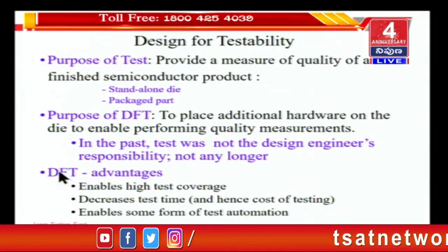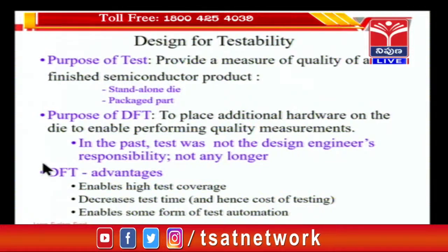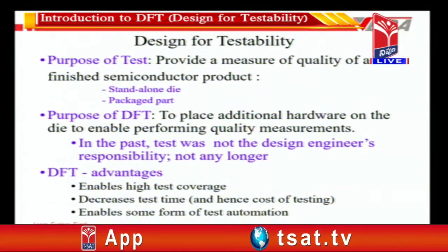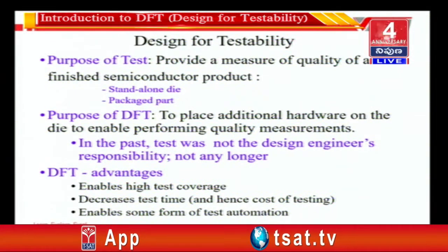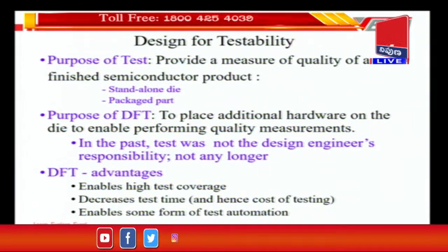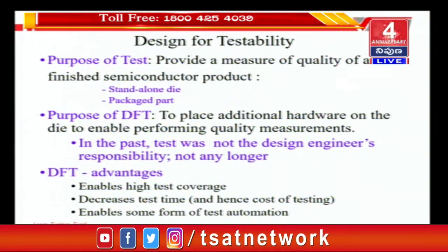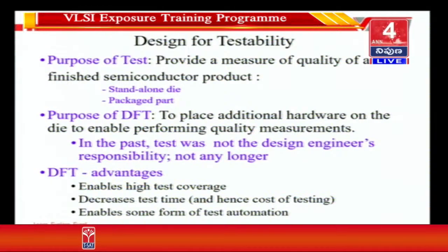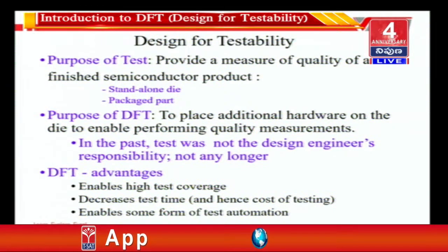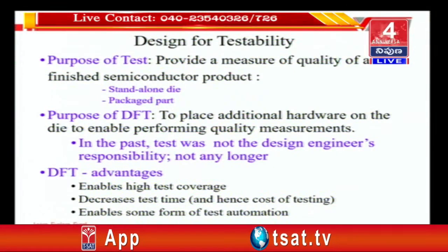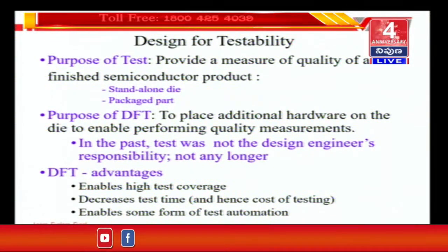The advantages of DFT as a collection of methodologies. When you say methodology, basically it is a structured way, maybe an automated way of generating test patterns. You do not have to write or generate test patterns manually. These test patterns will be automatically generated. That is why we have the term called ATPG, automatic test pattern generation, okay, or ATVG, some people call it automatic test vector generation in DFT, because the DFT algorithms work in these particular tools.